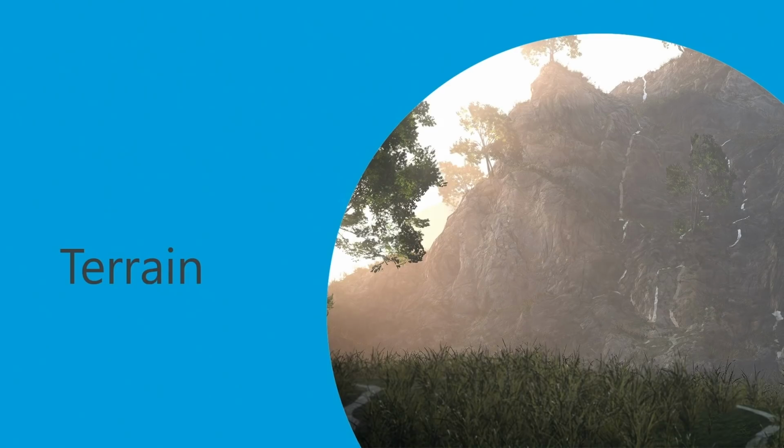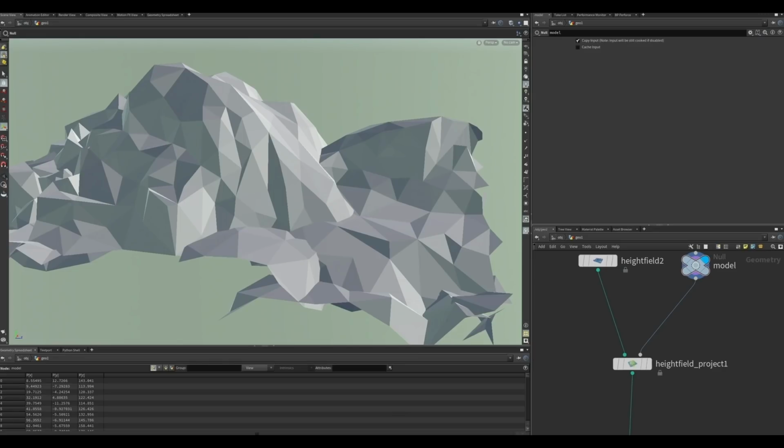So, going into the terrain stuff. One of the things that we get a lot with terrain is the art director will come in and say, I want a hill here, but it needs to have a slope at this kind of angle because the silhouette needs to look exactly like this. In a lot of other terrain generation software, you really lack that high level artistic control to get exactly the shapes that you want. Houdini allows us to influence the terrain based on custom input geometry, convert that to height fields, and use masks to do what we want to it.